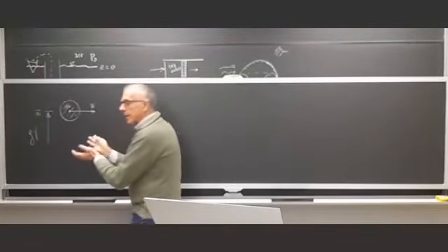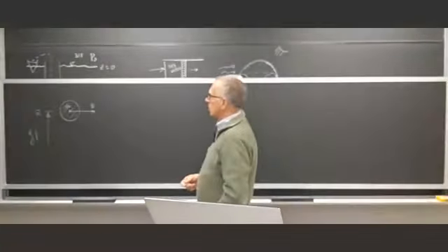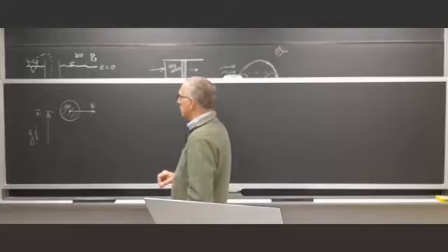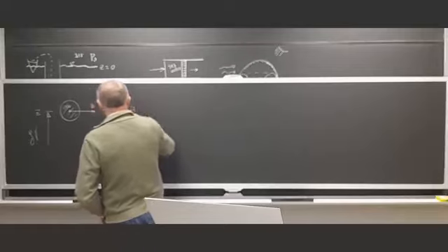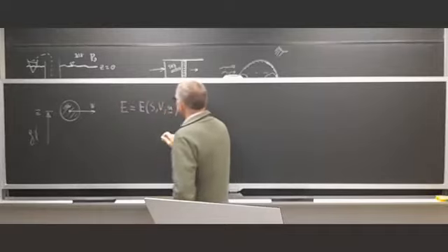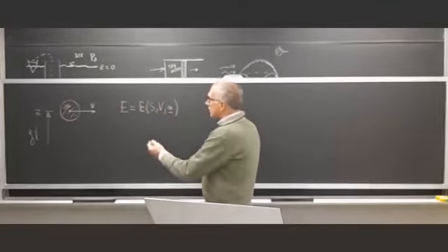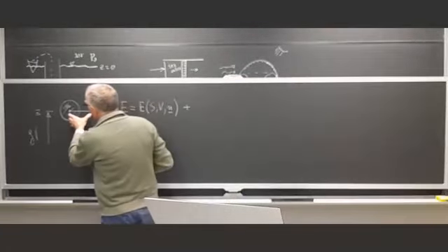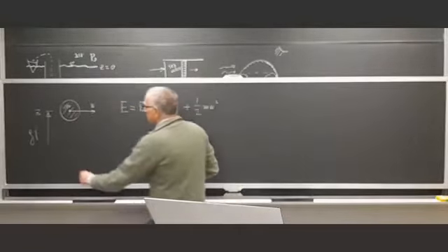When we do fluid mechanics, this is a fluid element or a fluid parcel, you call it, and we assign the properties in the local equilibrium assumption. We assign the properties of this fluid element by assuming that its energy is the energy that it would have with the same composition, volume, and entropy in a stable equilibrium state. Plus, we add these mechanical effects that are the kinetic energy and the potential energy.